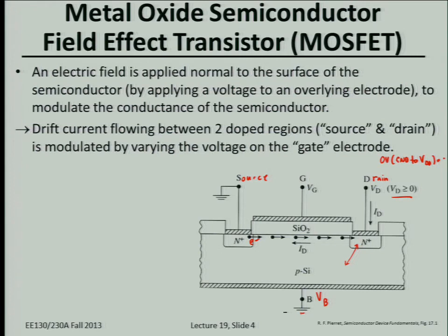And later, we are going to talk about body biasing, slightly adjusting the body bias to tune the threshold voltage. So in some products, people do actually purposely bias the body to be not at ground. It could be positive, could be negative, slightly above, slightly below 0, to tune the threshold voltage. And that's actually on your next homework assignment. But the biggest reason that we generally try to bias the body close to ground is just to avoid this p-n junction diode from turning on. Okay? Because we only want the drain current to flow if the gate is turning on the channel. That's basically the bottom line.